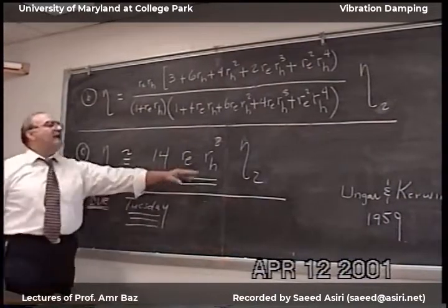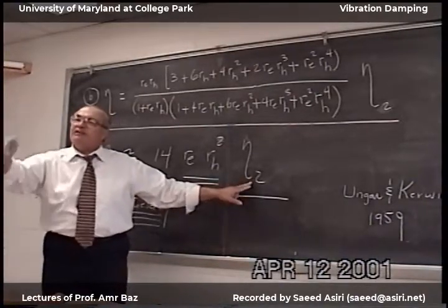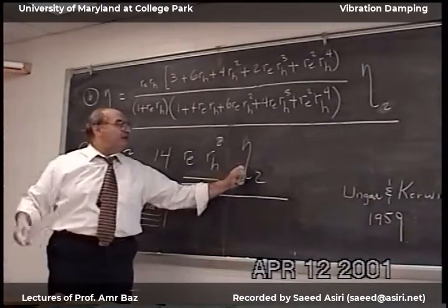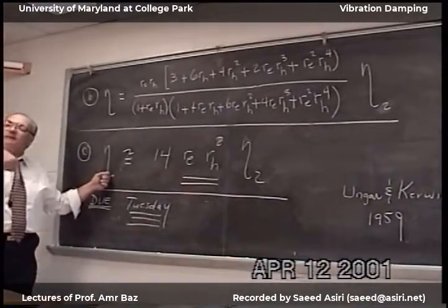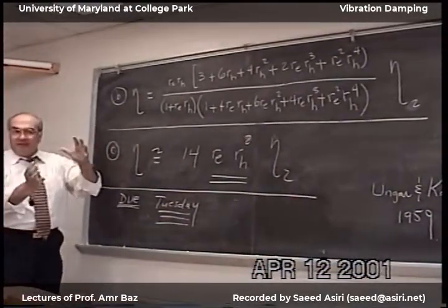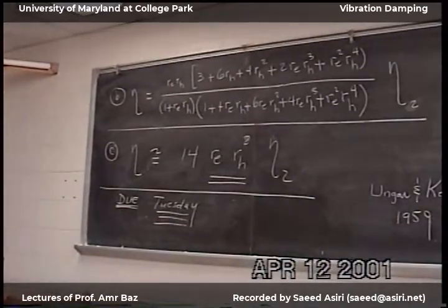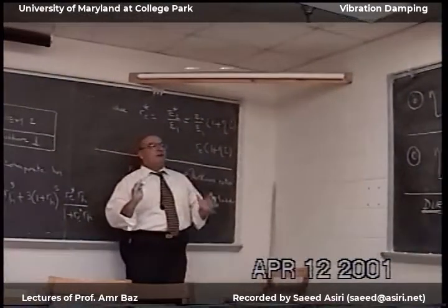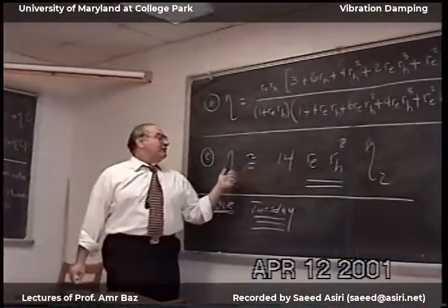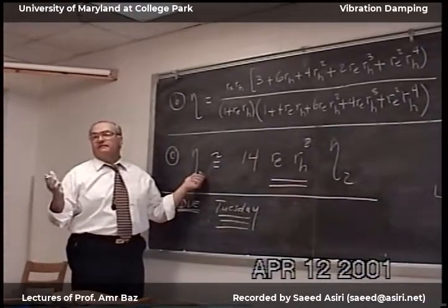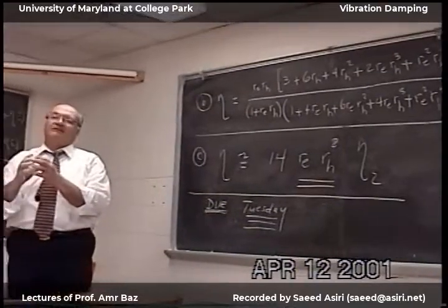Now loss factor of the viscoelastic material depends on the frequency. So at any resonant frequency, you determine from the table of the material E2 for the viscoelastic. Multiplied times this, you determine the corresponding value of the assembly of the structure. This also relates very nicely to some work that is done on how to calculate the loss factor of material using finite element. Finite element codes don't have viscoelastic material elements.